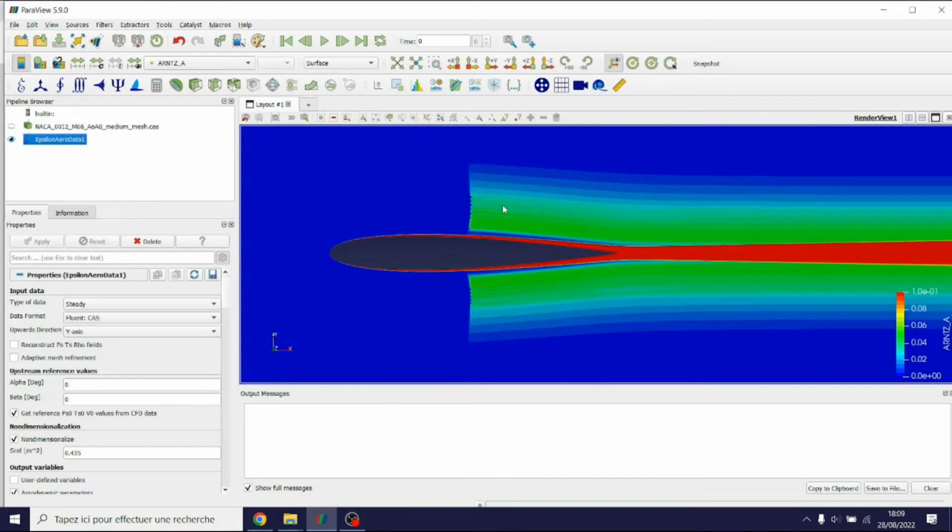So I can see the losses across the shockwave that are provided along the wake of the shockwave in green, and in red I can see the losses that occur inside the viscous region that are provided downstream along the viscous wake. So the main objective is to separate both parts, the green part from the red part, so I can actually have the shockwave drag and the viscous drag separated from the entire profile drag. And that can be achieved by using our specific filter.